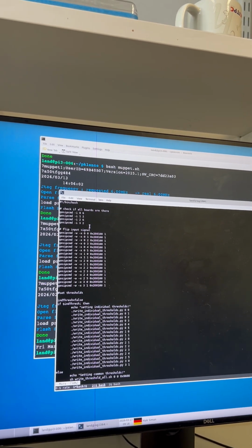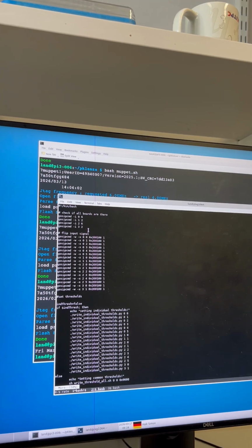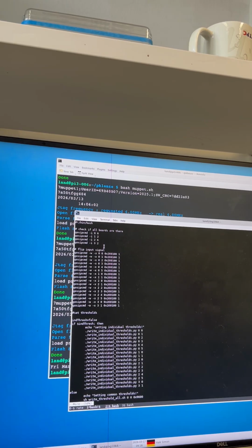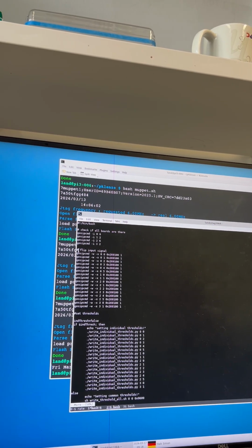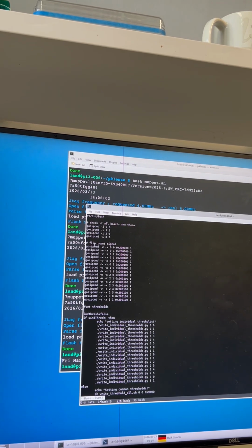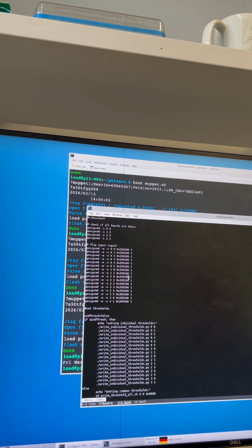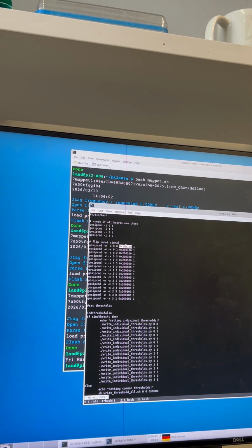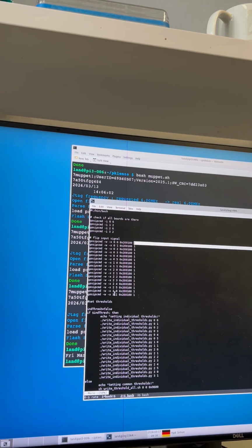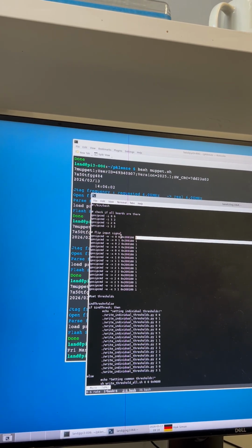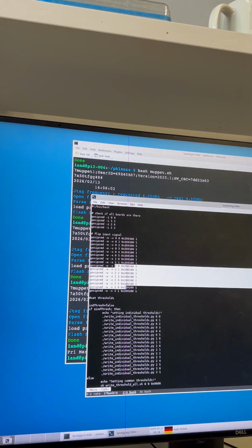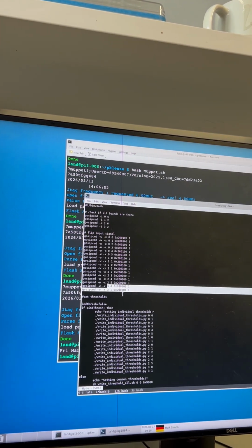But one can also arrange this. We have 4 readouts, 4 SFPs, and they are connected like that. So then every board needs to flip the input signal. You can choose positive or negative input signals. And in our case, we have to write in this register a 1. And you have to do that for all boards. So from 0 to 5, 1, 2 boards, 2, 6 boards, and 3, 2 boards.